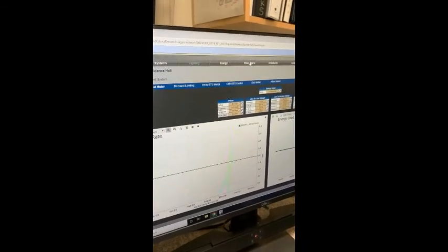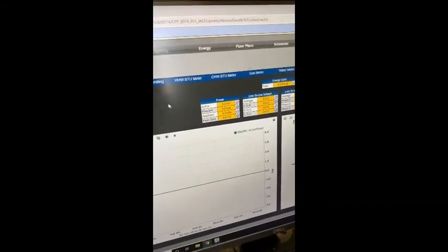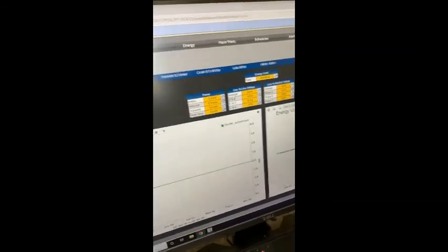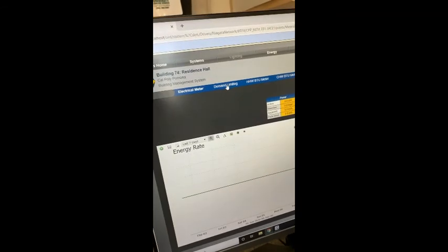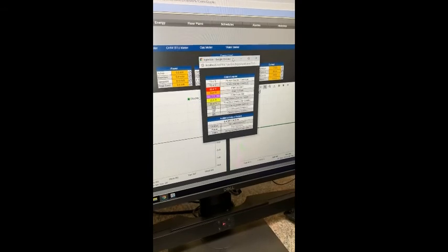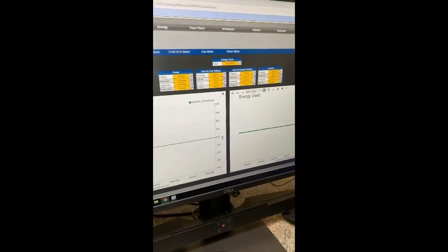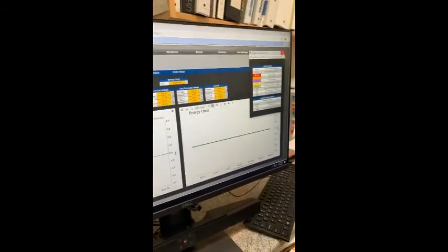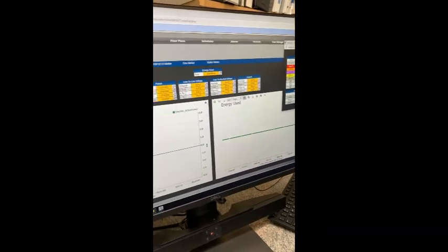There are some energy monitoring points. I know the IT department still hasn't got it so that we can actually talk to the electrical meters. That's why you'll see that these points are this yellow. I think it's technically goldenrod, but it means that the point's down because there's a communication failure, and it's on the IT side.